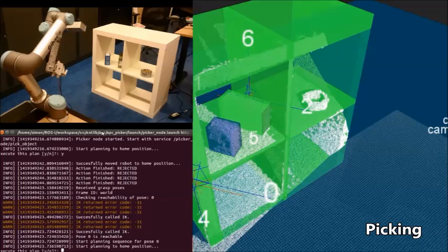For the selected object, the robot loads a set of pre-learned grasp positions and orientations that can be used as targets for the end effector of the robot, indicated here by the colored arrows. Not all targets are feasible. Some might simply be outside the reach of the robot, or the target could be infeasible due to obstructions of the shelf or other objects.